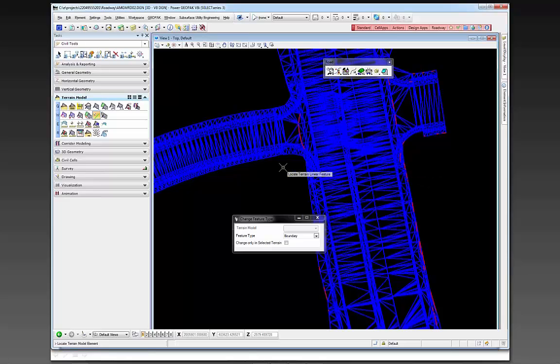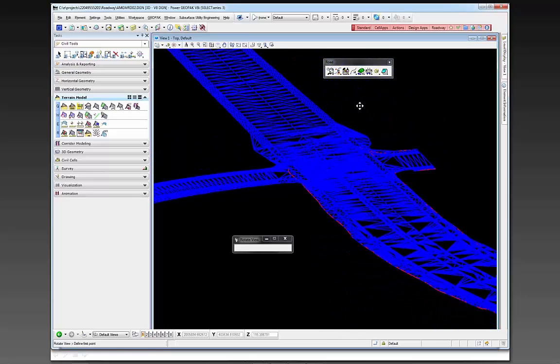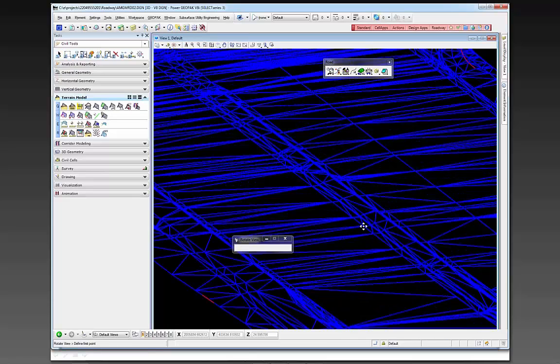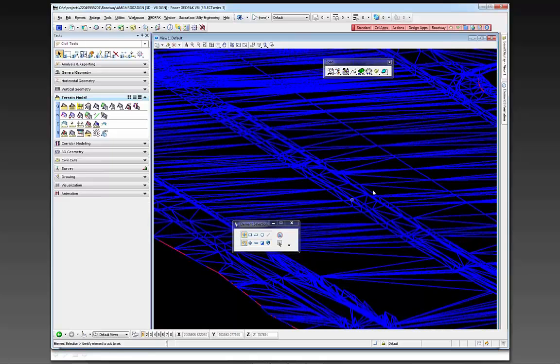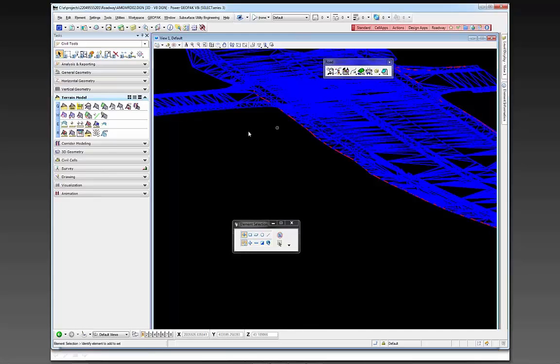Once you have those, you just isolate your cut fill lines and add them back into boundaries, and then it retriangulates and you have your proposed surface for that particular part of your proposed design. And it is a 3D surface. If you zoom in here, you'll see there's my traffic separator and my curbs, and all the detail is there. So once I have a terrain, I can use the same export to file function.